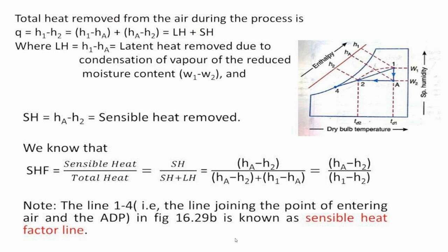Now in this slide we will see about sensible heat factor. What is sensible heat factor? Sensible heat factor is sensible heat divided by total heat. It's actually the ratio of total sensible heat upon total heat, where total heat is a combination of sensible heat and latent heat.